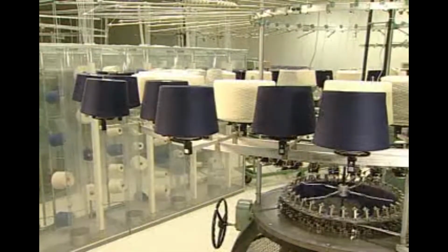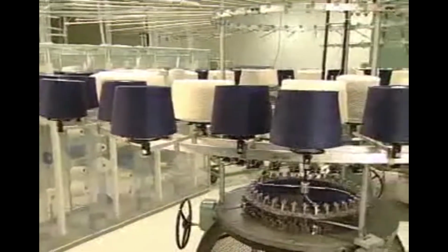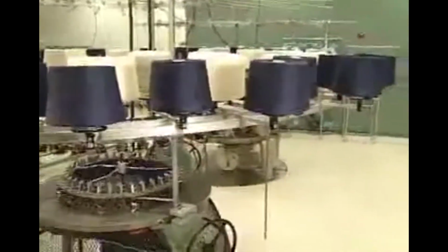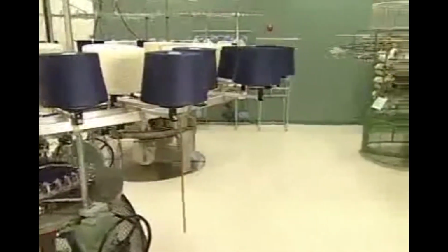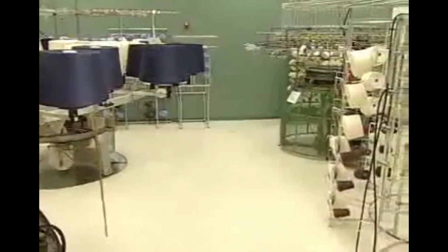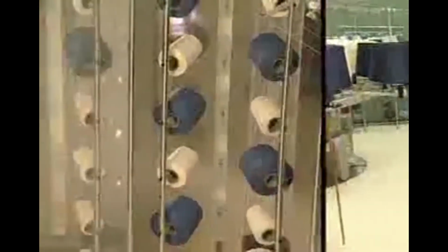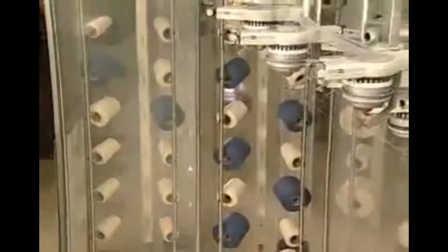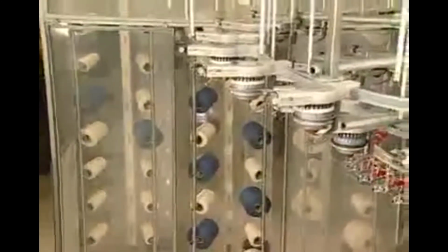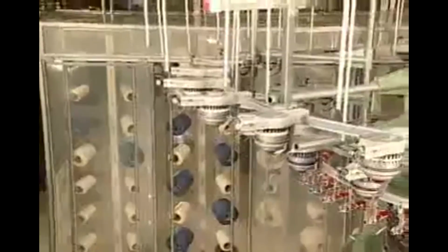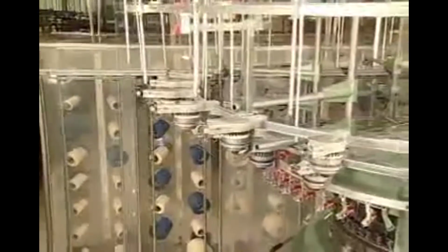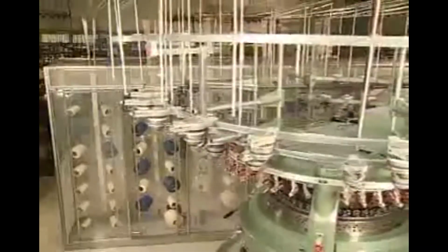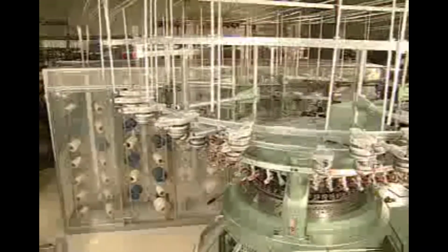Let's start by taking a look at the big picture, the basic configuration of most knitting machines. Commonly used for single knits are circular knitting machines, which pull their yarn supply from creels located either above the machine or next to the machine. To make it easier for technicians to service the creels, it is more usual to find creels located at the side. In this position, less lint falls into knitting elements. Larger packages can be used, and more feeds can be placed on the machine.